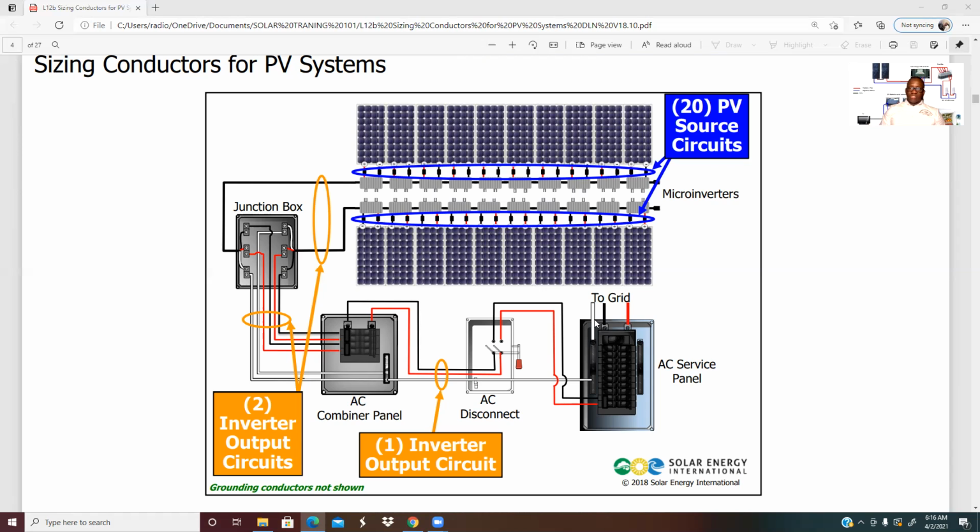Now, if you notice, there is not an inverter in the house, because from the module, the DC has been inverted to AC using the microinverter. So directly coming into this home are all AC runs, complete AC runs. The lead sends all of these runs into the home, all AC runs.